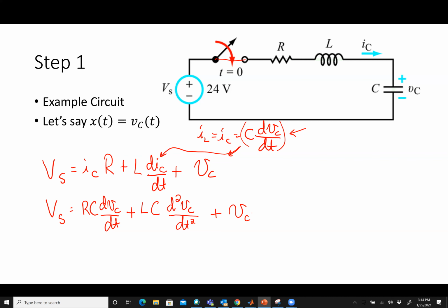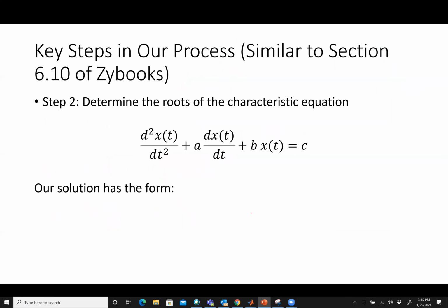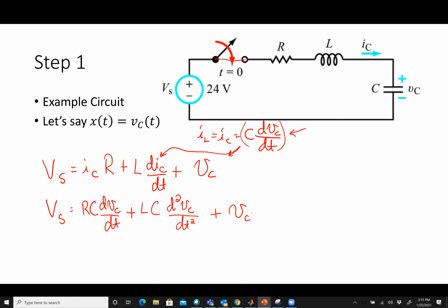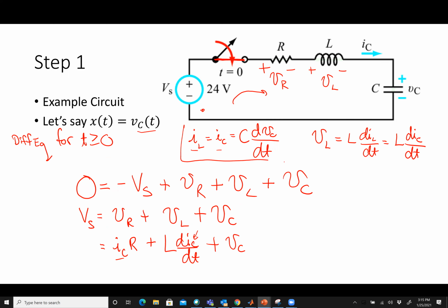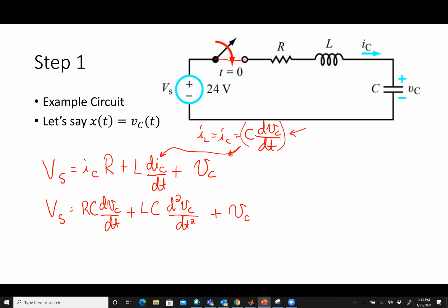Anytime we're looking at these circuits, and we're going to look at lots of examples of them as we go, what we need to do is essentially write out a KVL or KCL in some way, and then use the relationships, this one here and this one here, to figure out how we can manipulate it. And I should be careful, it's not always the case that IL and IC are the same. It all depends on the situation. Those boxed equations are the ones that are always true, okay? All right. Now, is that in our standard form?